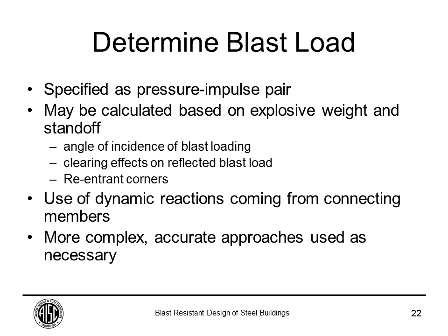So let's just talk about determining the blast load. Typically, the blast loads in a project are going to come in a specification, or if you're doing a DOD, it's going to tell you what kind of charge weight and standoff you have to use. So the main two approaches for determining your blast load: it's usually specified as a pressure and impulse pair, we're going to see that in the next slide, or you may calculate it based on an explosive weight and a standoff.